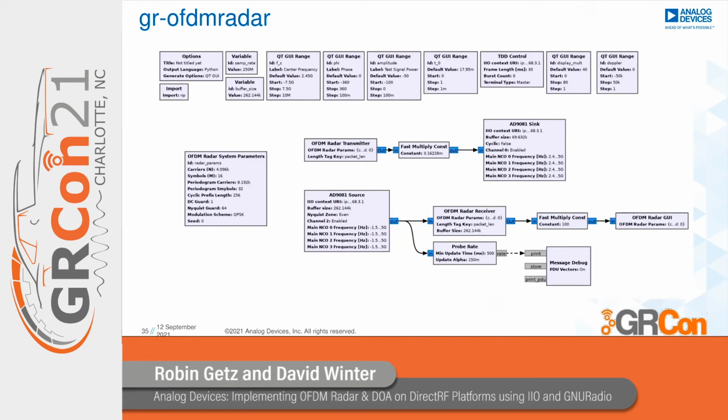The demo setup, which used actual hardware, is very similar. We just have replaced our channel model with an AD9361 sink and source block, and introduced the TDD control block, which is used to control the buffer alignment of the transmit and receive buffers, as I explained earlier.